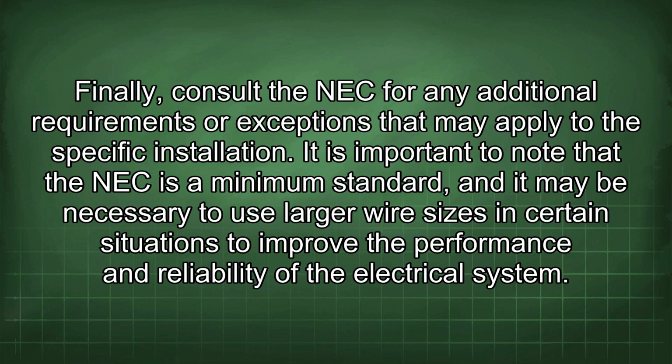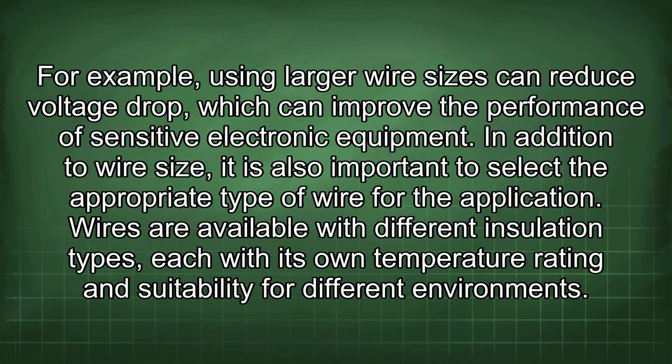It is important to note that the NEC is a minimum standard, and it may be necessary to use larger wire sizes in certain situations to improve the performance and reliability of the electrical system. For example, using larger wire sizes can reduce voltage drop, which can improve the performance of sensitive electronic equipment.